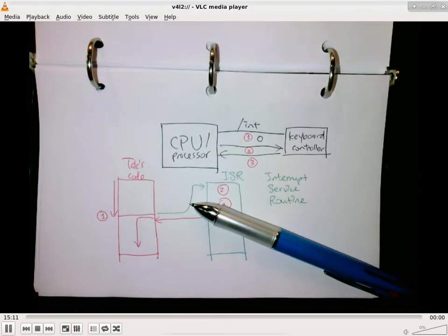The green line is representing an asynchronous event, which means from the software perspective, it has absolutely no idea when it is going to happen. Okay? So I cannot prepare for that. I can only do my best and say I'm just executing my code. When the hardware interrupt happens, my code doesn't know anything about it. The processor in hardware is taking care of the transition from my code to the ISR, to the interrupt service routine.